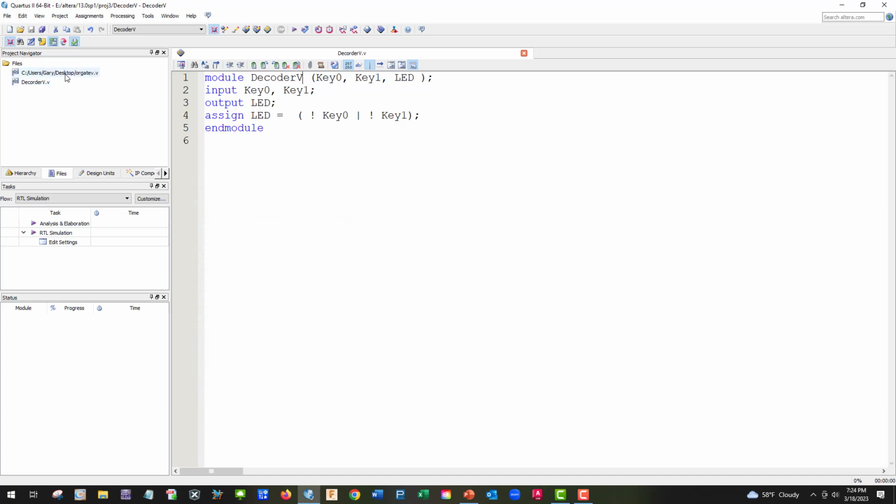Yes, we're going to right click this, remove it from the file, and we need to put in all of our inputs: B, C, D, E, F, G. Already have a comma, so let's copy. And our input is going to be all those. That looks good. Assignment LED, that's fine.